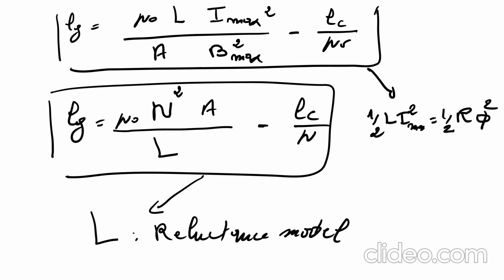is because the air gap is independent of the cross section of your magnetic core. That's the common mistake that most engineers, and also professors, make, as I have seen in most of the lectures you can find online. They consider the cross section as a variable that the air gap depends on, and that's not correct.